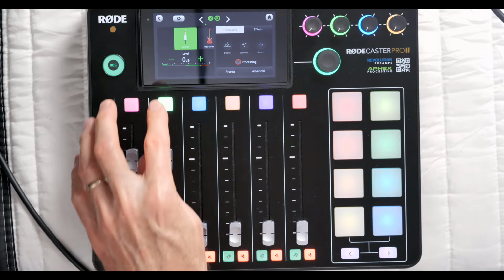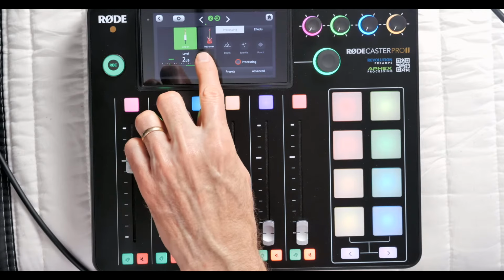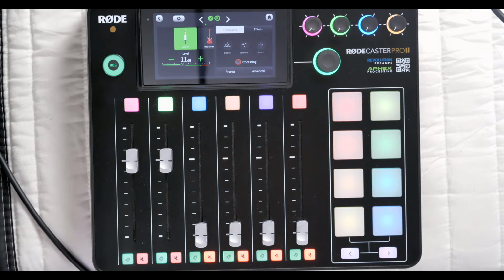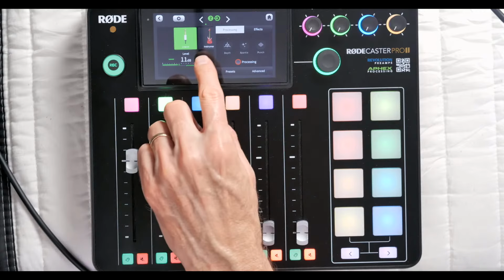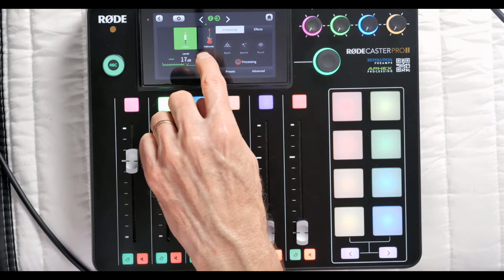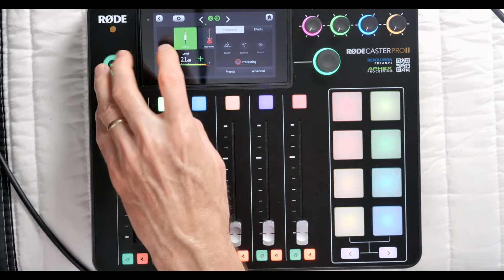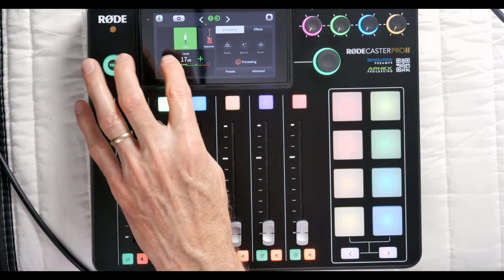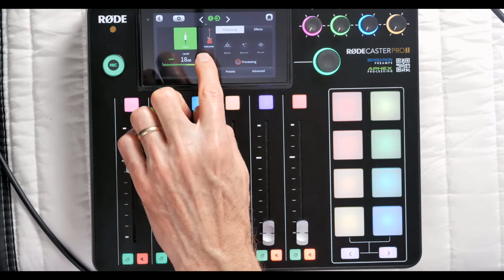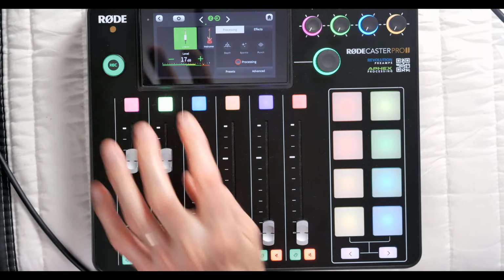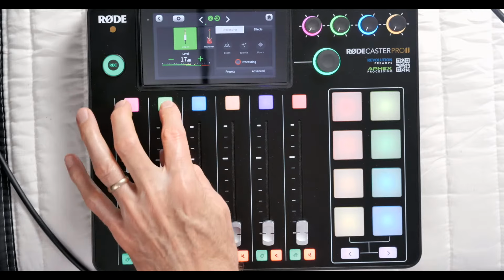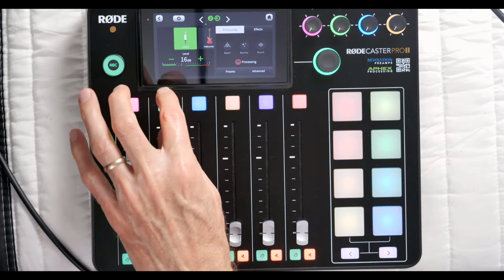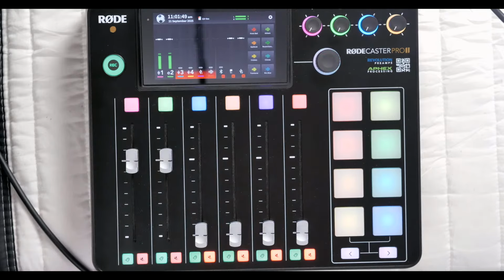It's showing very weak. The RODECaster, I don't know how Rode is defining line level on this, but it doesn't appear to be line level. So I always find myself having to add a good bit of gain. So, well, 21 might be too much. So there's 17 dB of gain. Whoa, it suddenly jumps. Okay, let's come back out, see what we've got here. Let's gain that down a little bit. Checking 1, 2, 3. Okay, there.